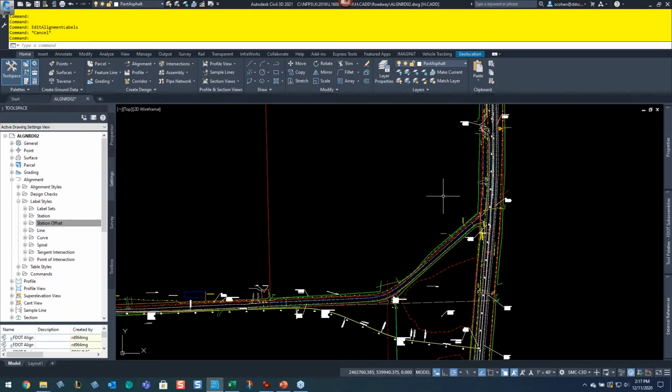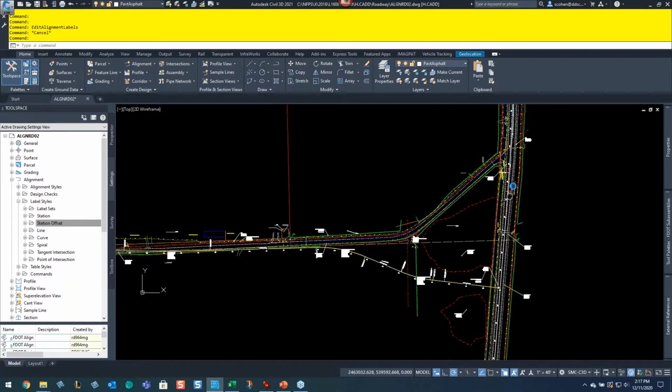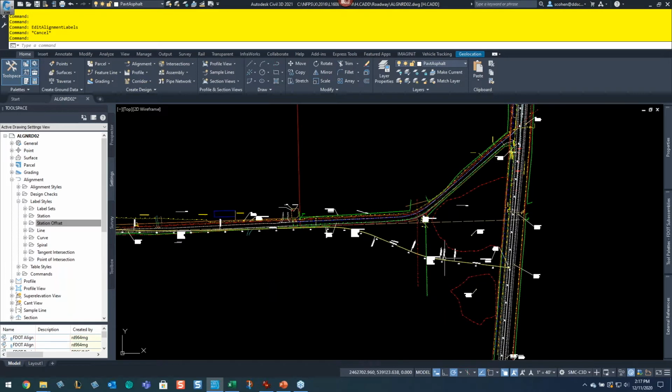So obviously, based upon whatever criteria you want, this is a DOT road here. This is a county road. So there are certain criteria that you have to make sure that you apply. Like you have to be at least a minimum of, I think it's 500 feet or whatever it is, from entrances. DOT usually doesn't want to give you additional ones depending on how it's classified, that type of stuff. But we were far enough away from this, and we basically put it in here. This is the only way that we could get this road in here.